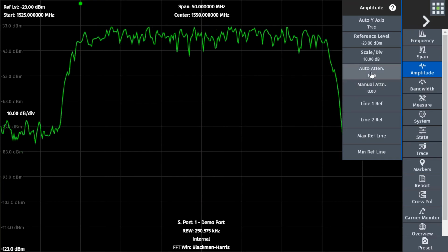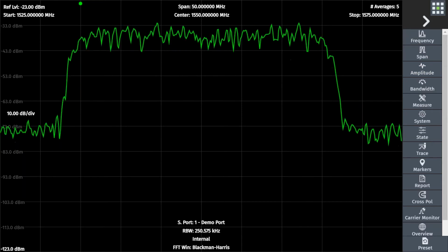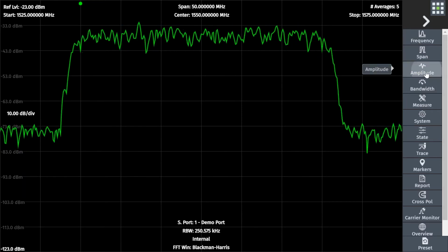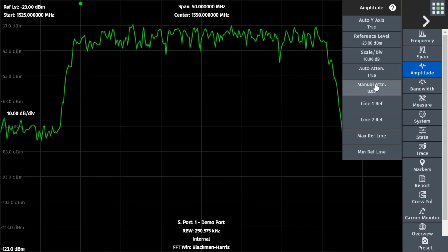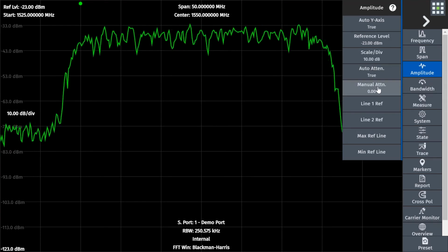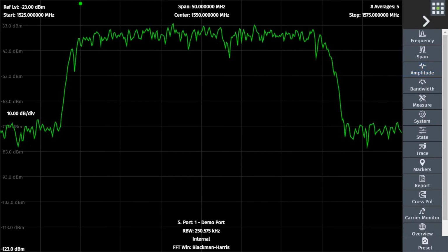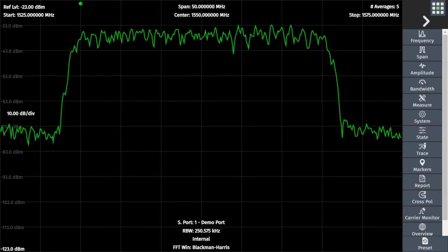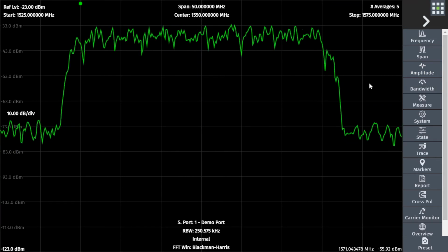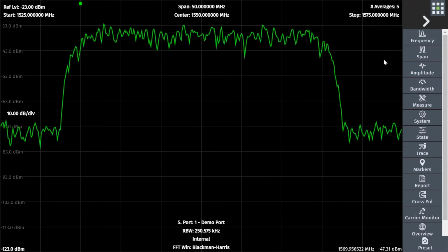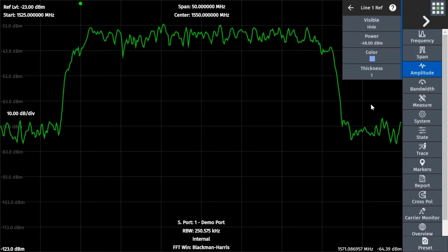And there's also attenuators inside the unit to control the dynamic range. Again, that's something that most people will leave in an automatic format, but if you do want to control the manual attenuation, that's also possible. It depends if you're doing some complex measurements of signals and you really want tight control on all your parameters, that's available. Although most people, like I say, if you're just looking at a quick snapshot of a carrier, the automatic settings are sufficient.